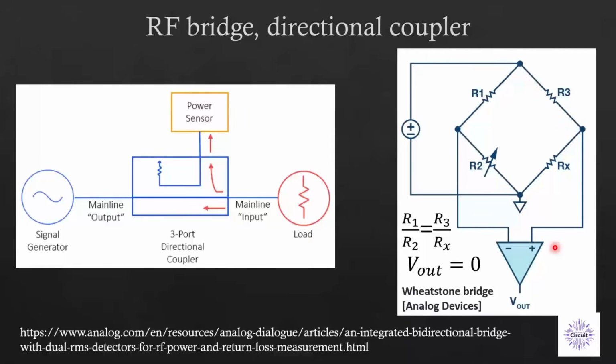If you want the voltage with respect to ground, you need to do a differential to single-ended conversion, requiring, for instance, here it's shown as an active amplifier, but if you want to use higher frequencies, sometimes they use a balun to create that differential to single-ended conversion, and that balun by itself has a transfer function. It's not an ideal differential to single-ended converter that can operate at all the frequencies. Or these resistors definitely have their own parasitics.